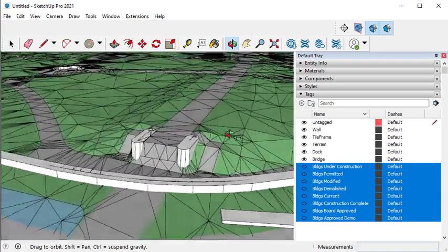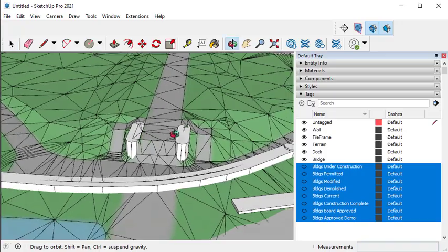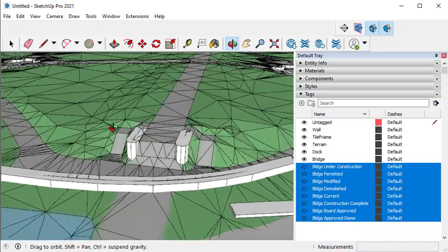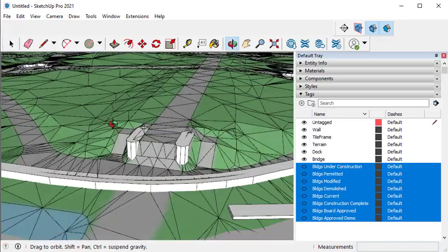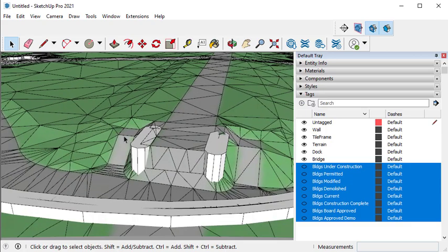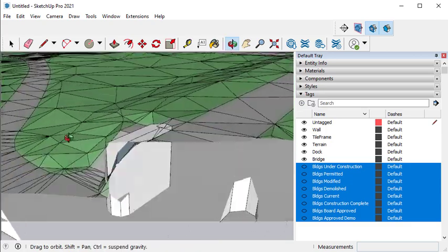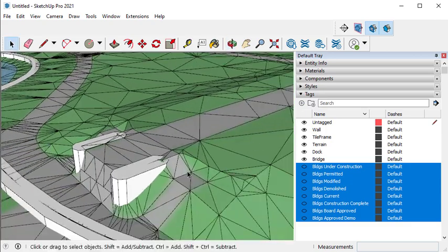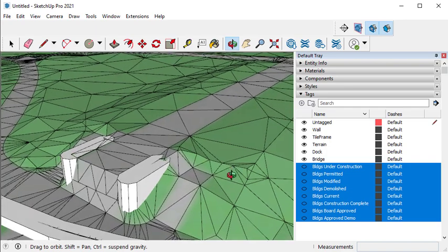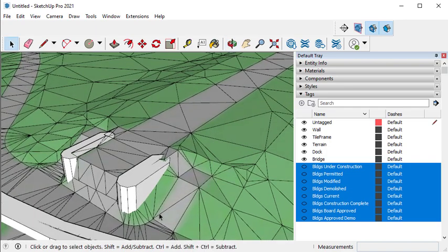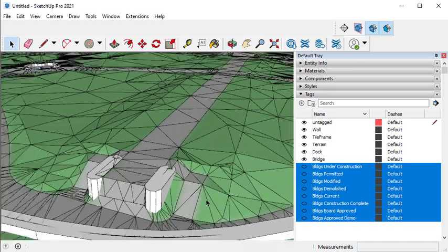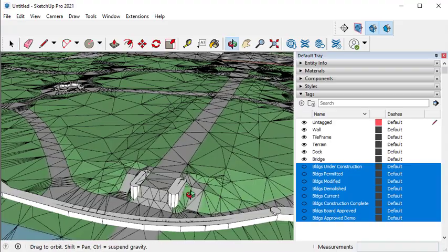It comes from a digital terrain model that's made of contours, break lines, and mass points. The break lines are most important. In fact, the contours aren't used here, but the break lines show exactly where this terrain should be creased. And the nice thing about it is that it is completely logically consistent with this ground plan, which was from the same photogrammetric survey.